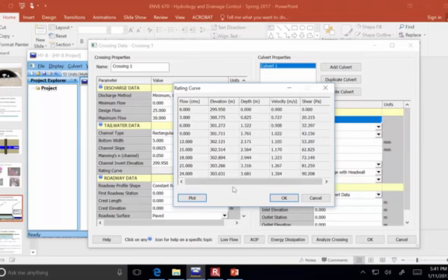So this is just calculating for, gee whiz purposes, if you're interested. One of the kind of cool things is it also calculates the shear stress, so that if you know what your channel downstream is made of, you can know if the bed is being suspended by the shear stress for a certain flow rate. So is it going to start washing away a sandy channel when you've got really high flow velocities and so on.